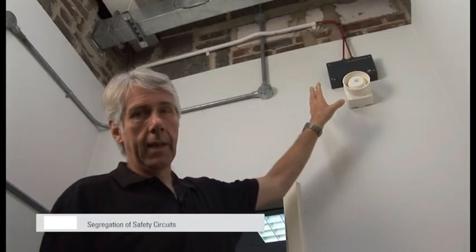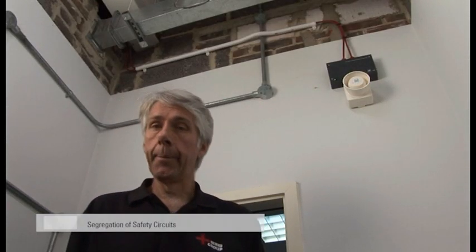With the next box, segregation of safety circuits, the inspector is making sure that these are segregated from other circuits and from each other. This typically means separating by a suitable distance, or more usually by use of separate enclosures, compartmental trunking, or one of the other methods detailed in Regulation 528.1. When designing the installation, the designer would have considered the protection of the safety systems from any electromagnetic interference. If special requirements have been specified, such as metallic shielding and certain types of trunking, then the inspector needs to verify that this exists.